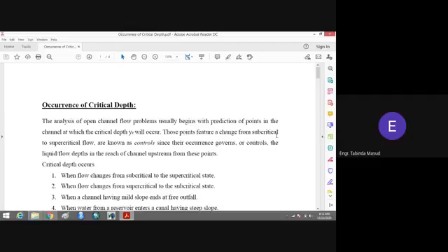One of the uses we can discuss here is this. Let's suppose there is sedimentation in a channel and you want to cope with this situation. First of all, in order to cope with the situation of the sedimentation, you have to find the state of the flow in a channel. Why? Because subcritical flow and supercritical flow behave differently for the sedimentation. We know that for subcritical flow, the depth of the flow is higher and its velocity is low.